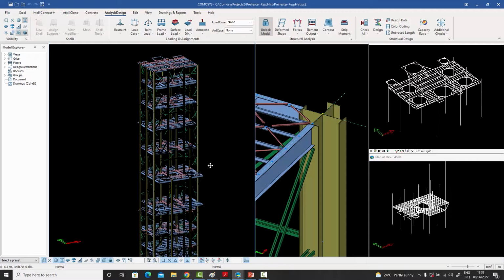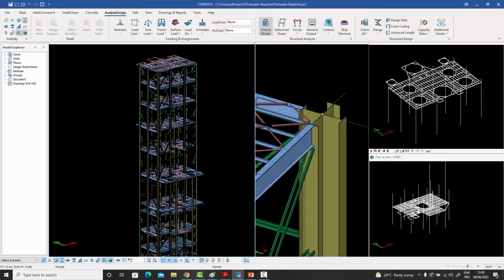Now, let's say we don't want to do a response spectrum analysis, but we wanted to do a time history analysis on this. Obviously, I personally prefer to do the response spectrum analysis in most cases, because they are much easier to deal with, and they create much less clutter. And one response spectrum can actually cover dozens of time history analyses, because if you select a particular time history, you would need to be very careful, because it might not represent the full spectrum of that area.